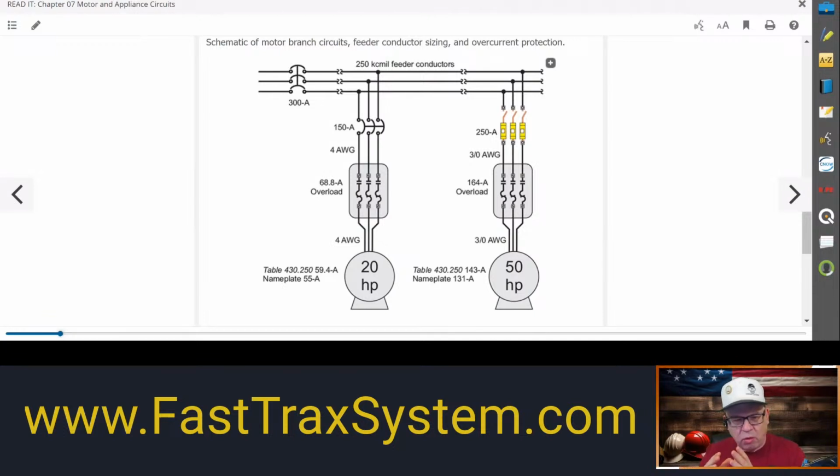So it's kind of like a worst case scenario. If somebody comes and changes this motor, and maybe it's even a more efficient motor as time goes on, if we traditionally size everything based on the FLC, then we know that we're going to be okay, and the conductors are going to be sized more conservatively than they possibly would be for an FLA, which is on a nameplate and can change for the motor. Why? Because it has to do with power factors, and all kinds of things can affect the FLA, but the FLC is constant. So if we're sizing things based on that constant, it's going to be pretty consistent.